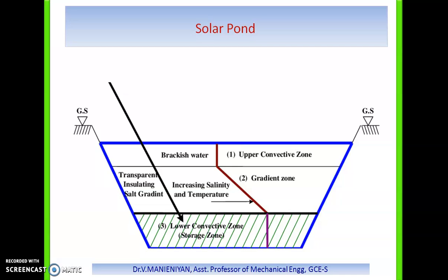The solubility should not vary appreciably with temperature. The solution must be transmissive to solar radiation. It must be environmentally safe with respect to groundwater. It must be available near the site, so delivery cost is low. So it must be inexpensive.